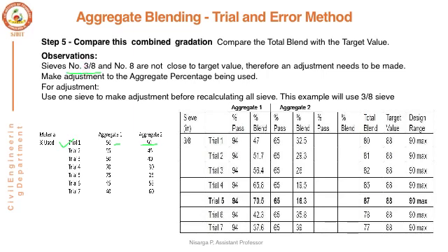We are working out for one sieve, and whichever value comes closer in this particular step, we will check that particular proportion for all other sieves. So here next, these two values 94 and 65 have to be entered in the column percentage pass, and then we have to obtain the percentage blend.